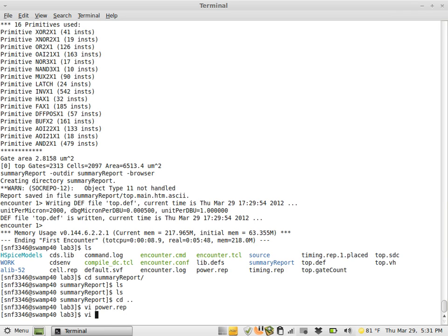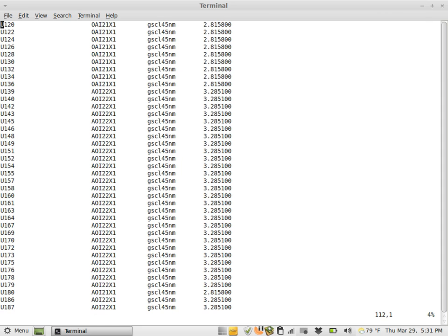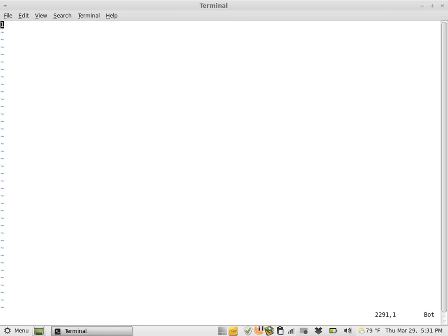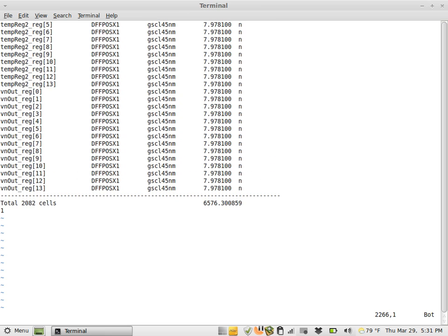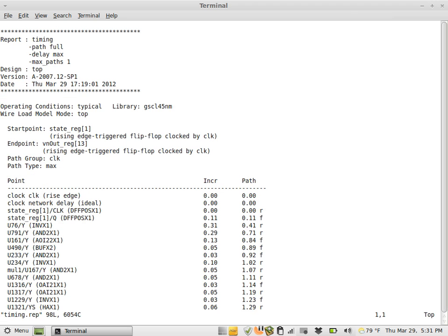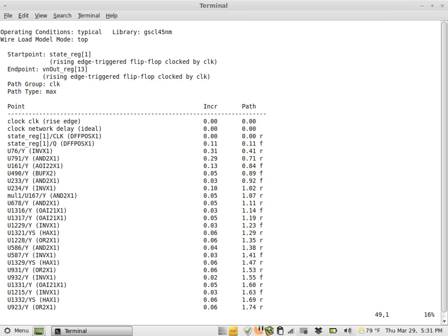So you have that, you have the cell report. It will tell you all the cells that you have. It will also tell you the total area from the cells. And finally, I have my timing report. The timing report you could use to see if you can increase your frequency or not.